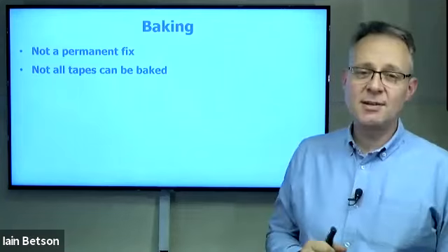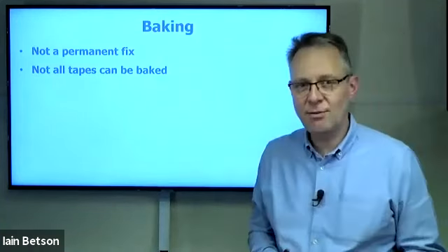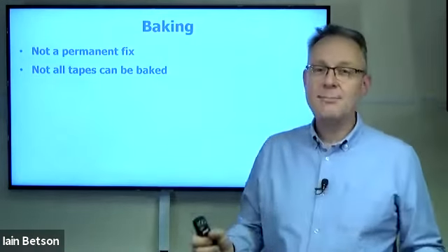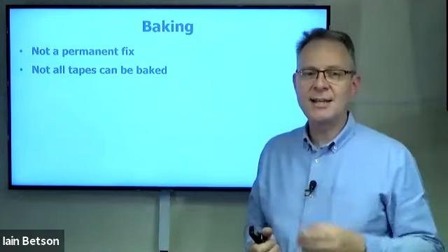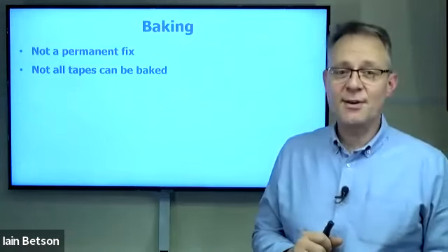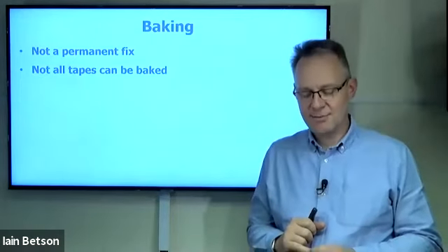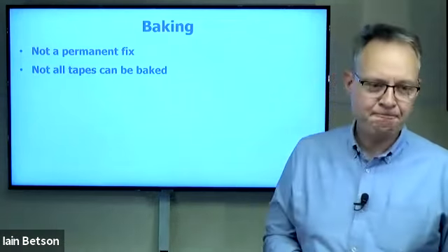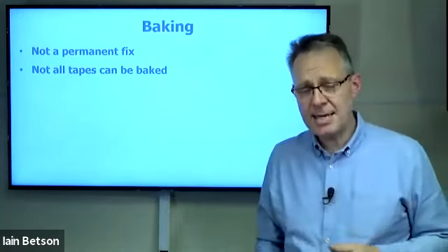built this sort of insulated stuff with a bit of rock wool around the outside, and just left it for 24 hours, switched the light off, left it for 24 hours, came back, took the tapes out. He maintained that went perfectly well in terms of baking, and I guess the Bob Dylan master tapes he was transferring at the time survived that okay. So that's baking for you.